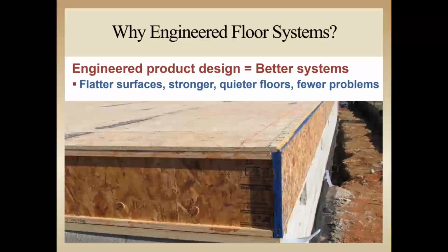I-joists create a flat system with all of the components exactly the same depth. With few variations in the joists and rim board products, the connection between the joists and subfloor panels is more direct by providing a smooth, uniform surface for the continuous bead of adhesive and nails so that all of the floor components are securely connected, and then they move together as a single unit. And as we all know, it's the independent movement of the components in floor systems that create noises and uneven floor surfaces.